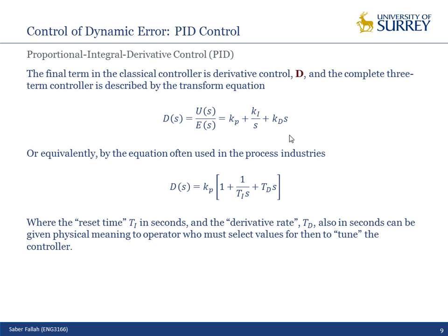If this noise comes to the controller, it gets the derivative of this value. What would be the derivative of this one? N prime will be 0.02 multiplied by 100 sine 100t. Look, the amplitude will be magnified 100 times. So even if I have very small noises, they will be magnified significantly by the derivative controller, which damages the performance of the whole controller.